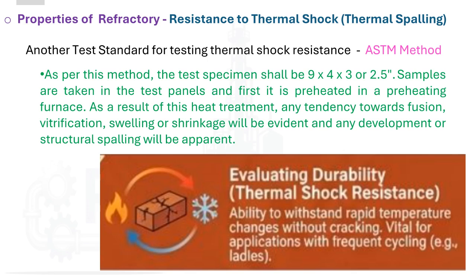And here is why this matters. Those crack patterns are diagnostic. An experienced engineer can look at how the cracks propagated and immediately understand the stress distribution, whether the failure was uniform across the brick or localized to a weak zone. In short, the ASTM method does not just measure resistance. It tells the story of how a refractory responds to sudden, violent temperature changes, giving engineers the insight they need to design linings that survive real furnace conditions.